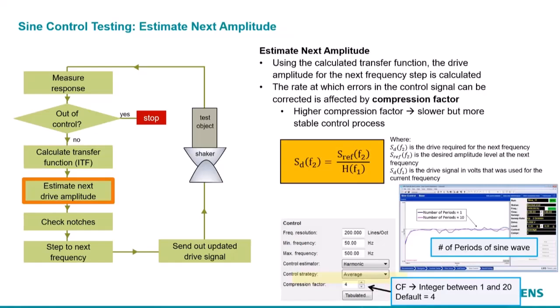And then we update the transfer function based on that calculation of the inverse transfer function. But sometimes if we have extraneous responses, we don't want to calculate drive output from the DAC to the shaker, to avoid spurious amplitude estimations and nonlinear resonant conditions. We want to dampen out the response of the transfer function and that calculation of the voltage. And we do that dampening through what's called the compression factor. If we want immediate, complete update of the transfer function, we use a factor of 1.